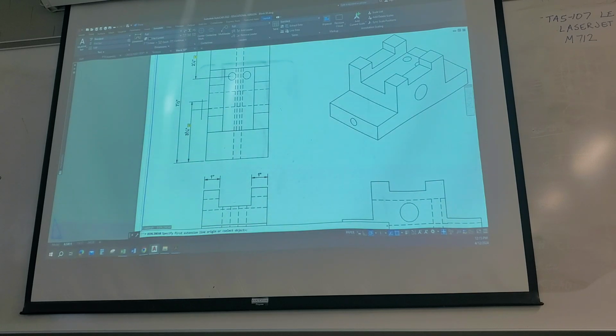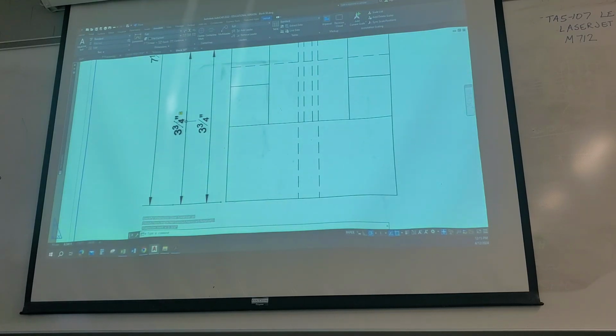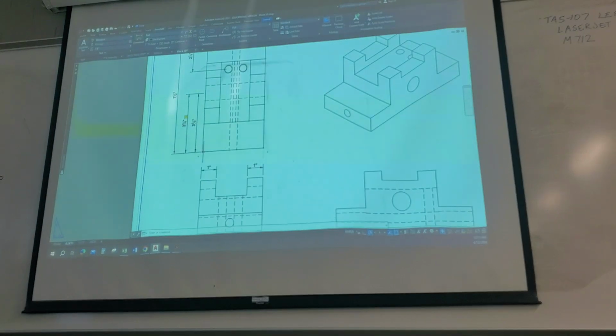If I would have gone through there and said, I don't want to go by that node right there, let me go to the midpoint here, and let me go to the end point here, now AutoCAD recognized two object snap points of that 3D object. AutoCAD will give me a good clean dimension. It's not that the other dimension was wrong. They're measuring the same points. We know that node is right there at that end point.